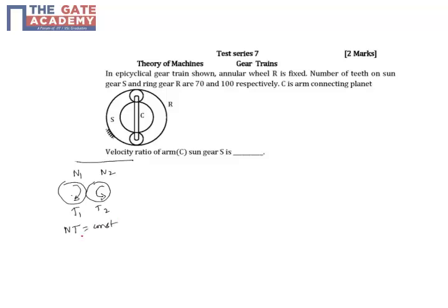To understand this directly, the tangential velocity at the interface is r omega, and that is the same for both. So r omega is constant, that is, the pitch circle diameter times the speed N is constant. And we know that the module is nothing but diameter by T. So diameter is m into T, and T into N is also constant because the module is the same for both. This is the indirect way of saying it.